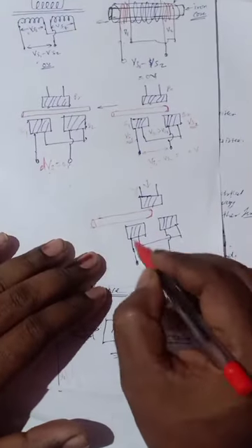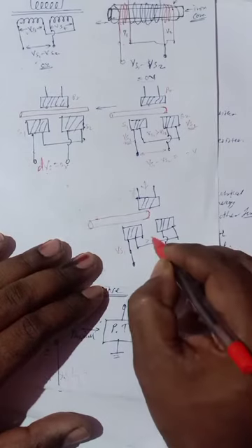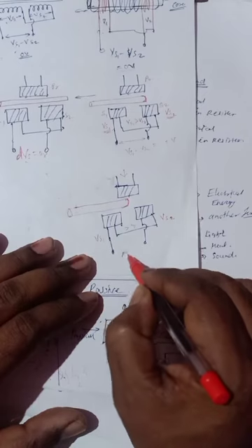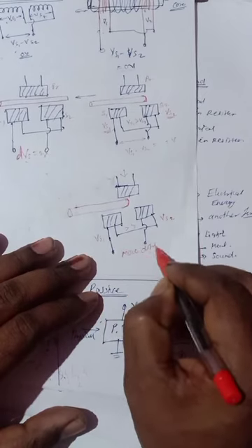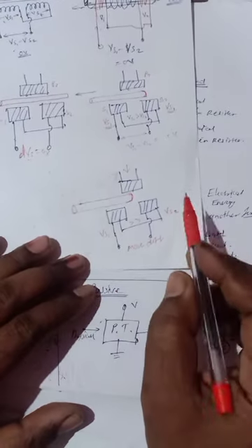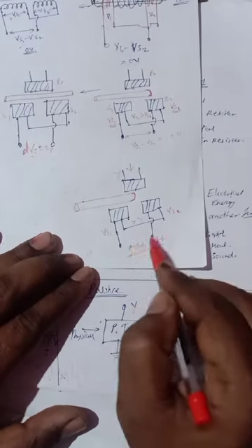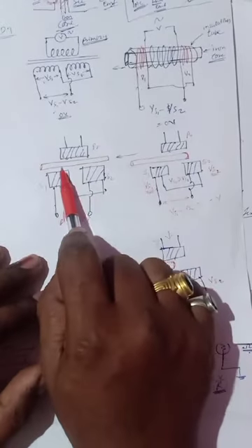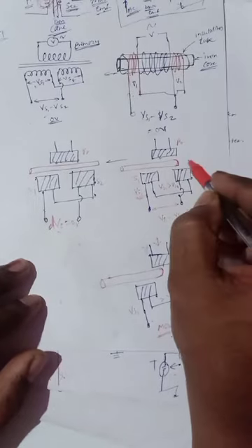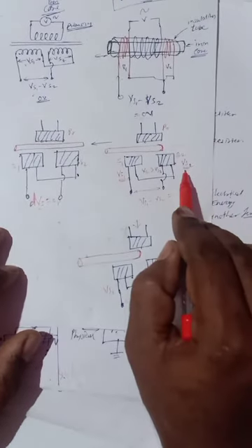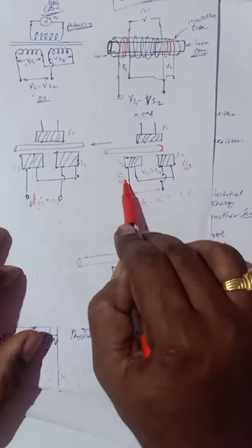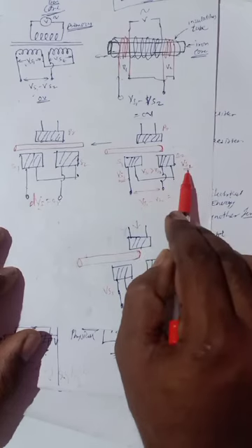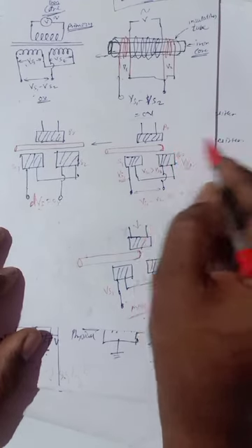In this case Vs1 is greater than Vs2, and we get a larger difference voltage, in phase with Vs1. Similarly, if we move this rod to this side, the Vs2 voltage becomes greater than Vs1, and we get a difference voltage which is in phase with Vs2.